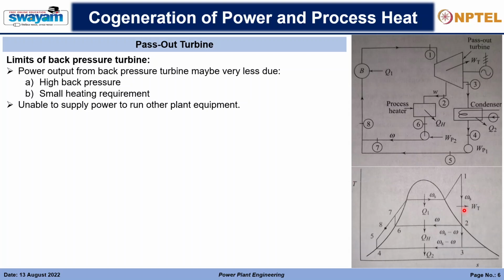Generally, the turbine expands to atmospheric conditions, the normal ambient conditions. So that is the normal. We will have to utilize the whole potential of the steam produced, right? But what we need is a dry steam state. So that is why we are stopping the full expansion by applying some pressure. By applying some pressure, we are not going to low pressure, actually we are stopping at higher pressure. So that is why we are applying some backward pressure. So this is back pressure.